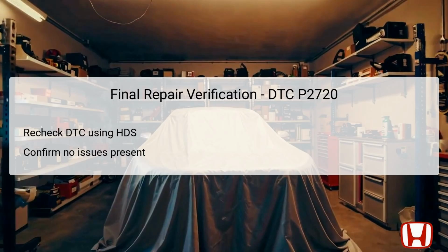After completing all necessary repairs related to DTC P2720, it is essential to conduct a final verification to ensure that the vehicle operates correctly. Utilize the Auto Diagnostics System, HDS, to recheck for any existing DTCs. This step is pivotal in confirming that the previous issues have been rectified and there are no lingering concerns within the system. A successful repair will show no return of DTC P2720 or other related codes. It's also beneficial to take the vehicle for a test drive under various conditions to observe its performance. If all runs smoothly, this indicates the repairs were successful and thorough, ensuring long-term reliability.